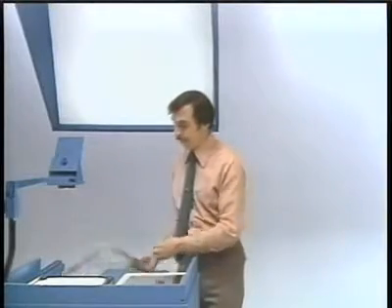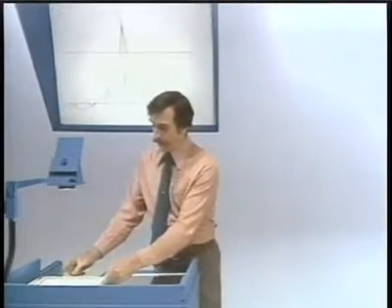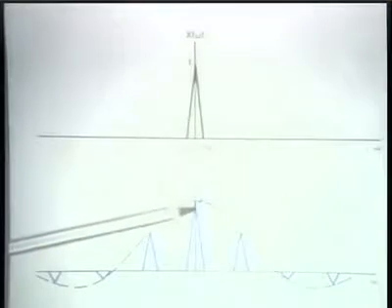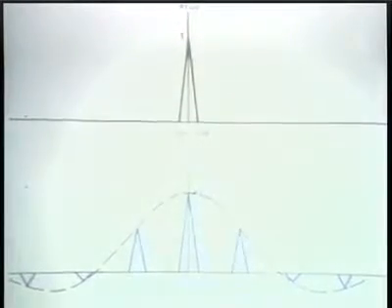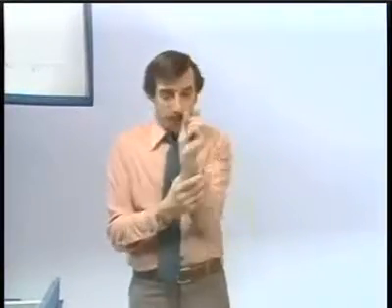Now, in practical terms it might. Looking back once more at the spectrum of the output, notice that this amplitude is proportional to delta, and what that suggests is that as we make delta smaller and smaller, which we might in fact want to do if we want to time division multiplex lots of channels, in principle, in theory, you could make it an infinite number of channels just by making that infinitesimally small. The smaller it is, in some sense, the less energy there is, and again, in practical terms, it's one of those things, if you push down here, it pops up there. Namely, you eventually run into issues such as noise problems.